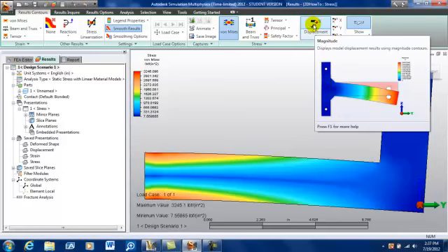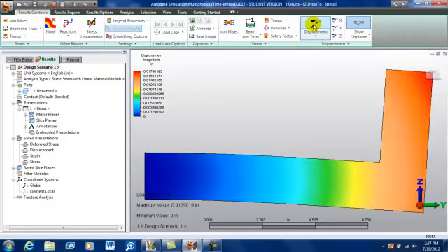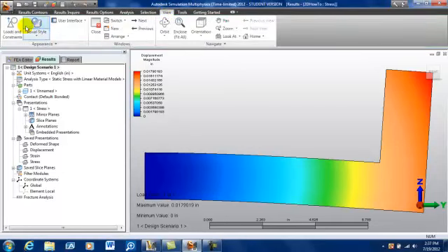Before I do anything else, though, I am going to check displacement. And displacement seems reasonable, 0.02 inches. Now, as I'm looking at this, I would like to go to View, and I do want to see my loads and constraints. You'll see where the pressure is acting and the direction where our constraint is applied.